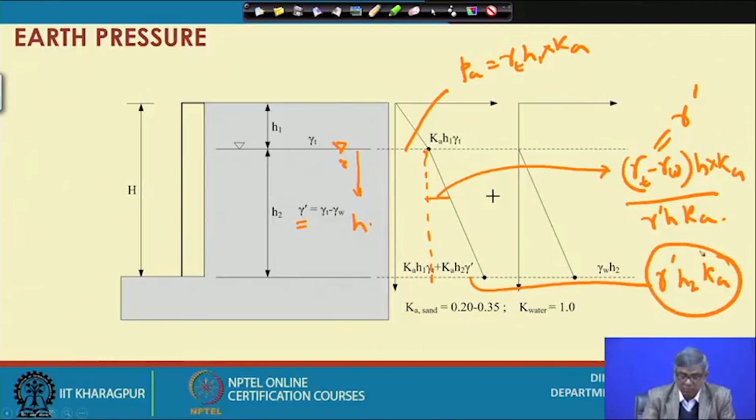So, from here to here, because of the soil weight, I am getting this component, and from here to here I am getting this one. Once this pressure is applied, this pressure will also be there, additionally because of this soil. So the diagram will be like this. That means I get a pressure diagram which is not a uniform triangle like previously. Now I can consider this a trapezoid, or I can consider one rectangle and one triangle. So in 3 parts it is easy to make it.